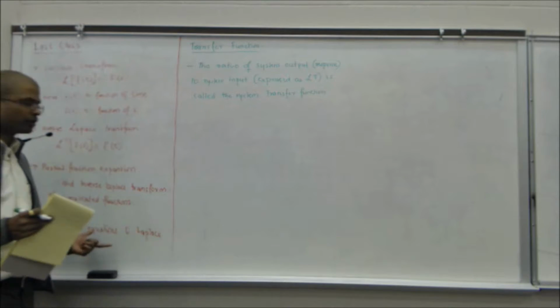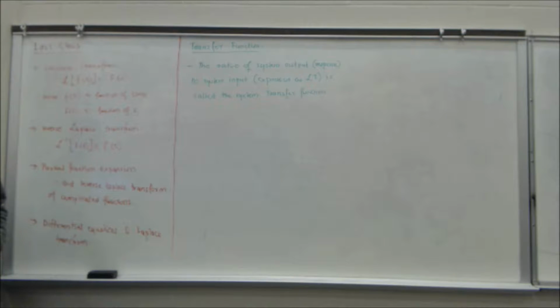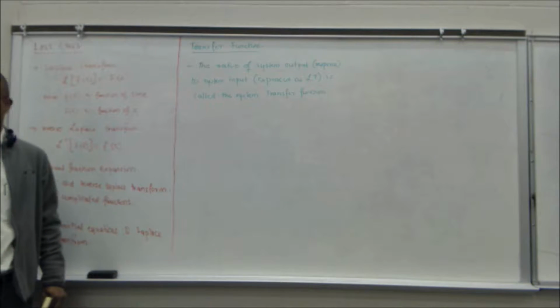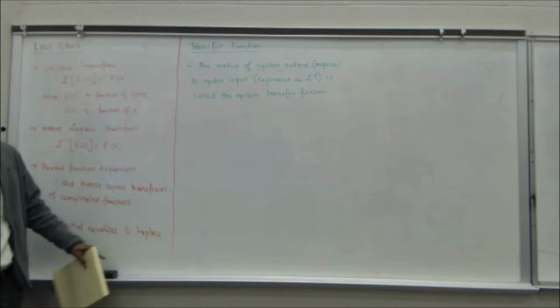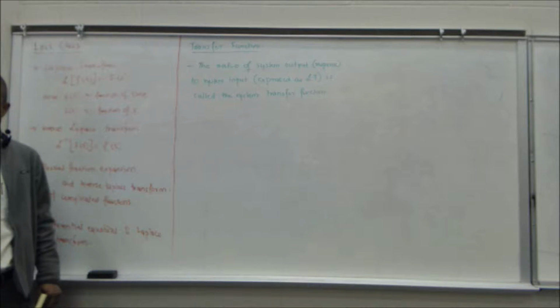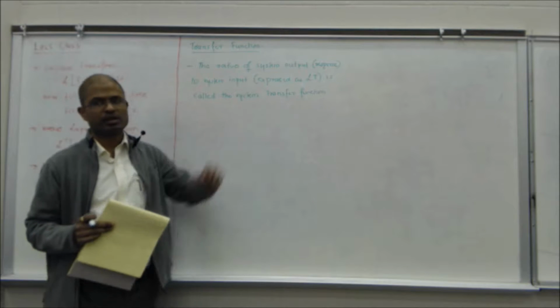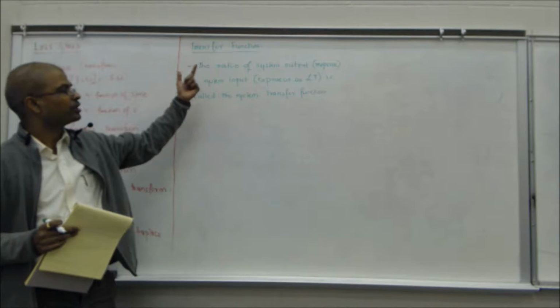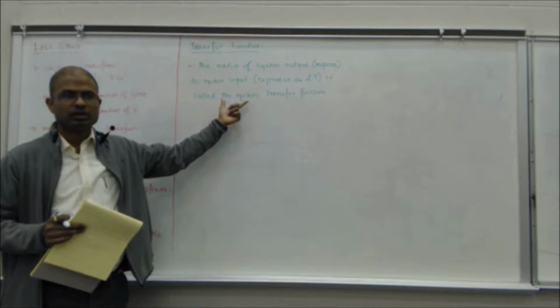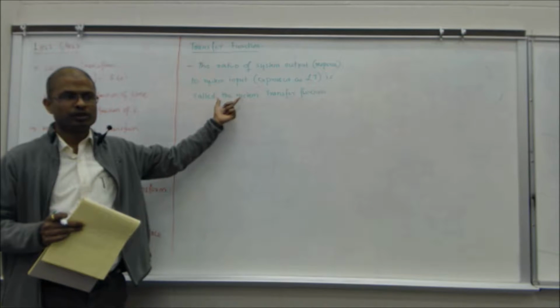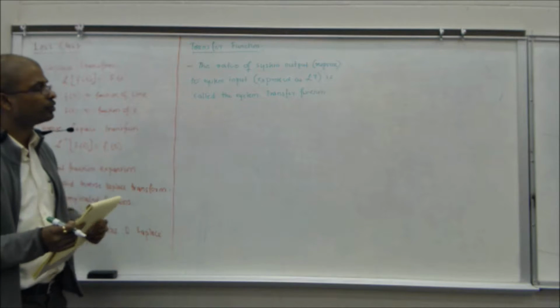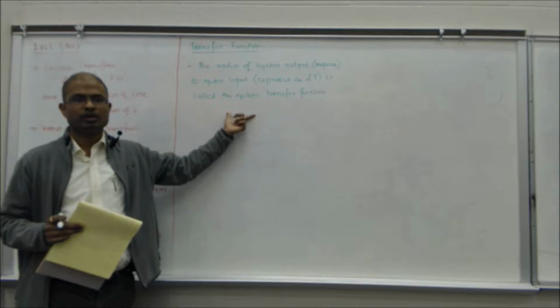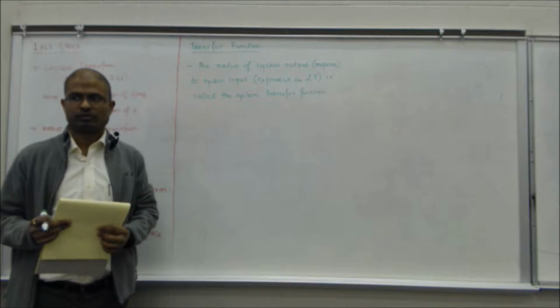And if you look at the differential equations, you cannot separate out the input and output, correct? But when we take the Laplace of that, we can actually separate the system output and system input. And that is the reason we say it is expressed as Laplace transform. So this transfer function exists only for a system expressed as Laplace transform. If you express the system as a differential equation, you cannot get a transfer function. Okay?